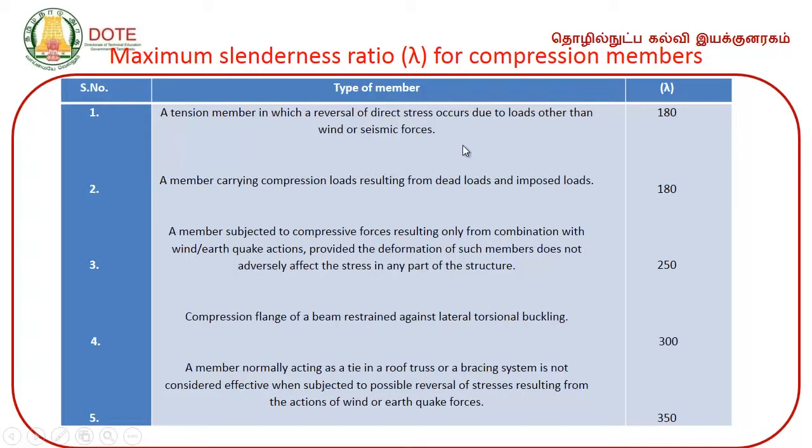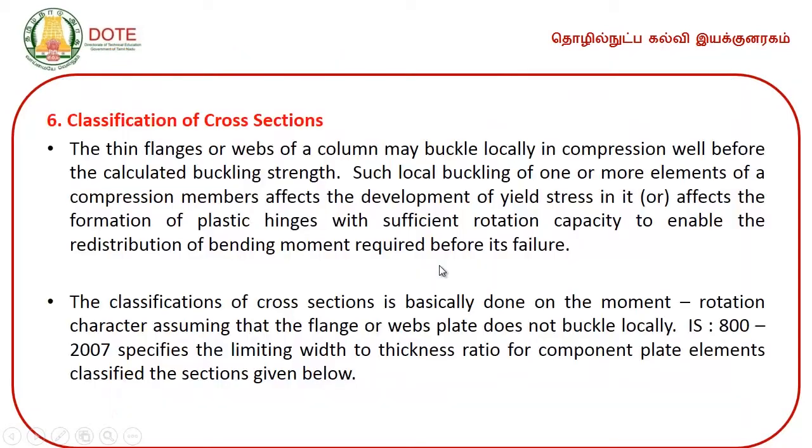This is lesson 4 on unit 5, steel structures, and so far we have seen the design of general and design of tension members and some introduction part about the design of compression members, and now we will continue. So, these are the maximum slenderness ratios for the compression members which are allowed as per the IS 800/2007. So, this is the tabular column which is taken from the IS code book, kindly refer to that one.